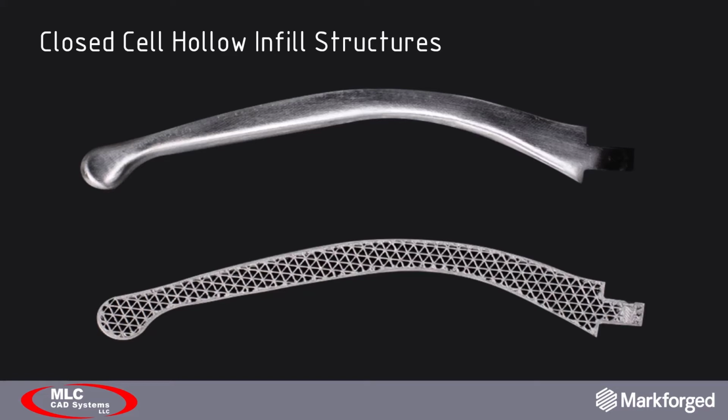Two, a part with the hollow infill structure uses less material and thus is essentially cheaper and it's faster to print. Three, the strength properties of the part are largely conserved when this type of structure is used. In most cases, a part maintains 85% of the strength versus a solid part. Fourth, the hollow infill allows for faster infiltration during the wash phase. The solvent used in the wash must make its way through the entire part, and the migration time increases exponentially as part thickness increases. In a nutshell, it makes the post-processing that much more efficient.